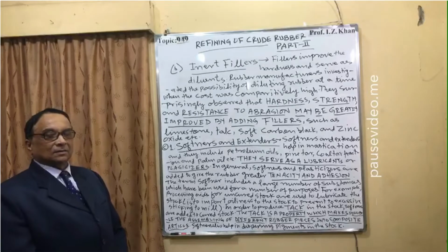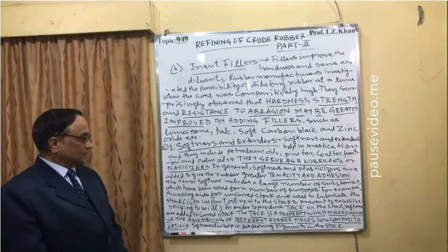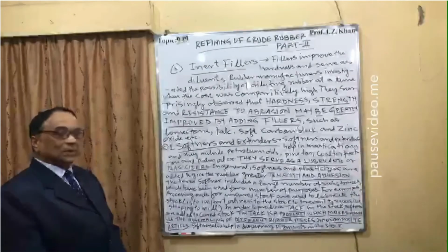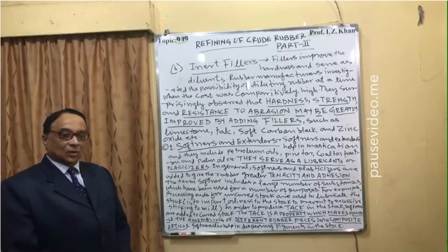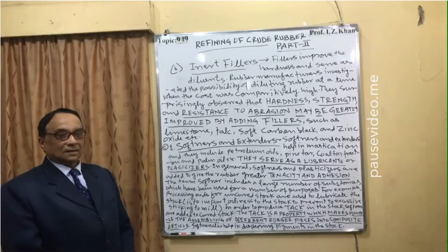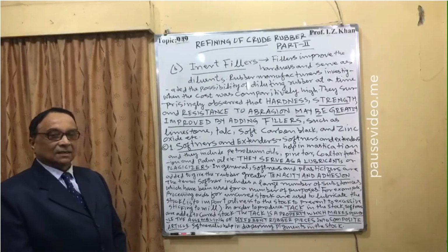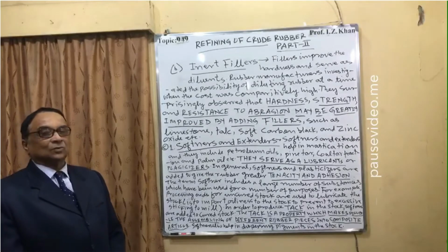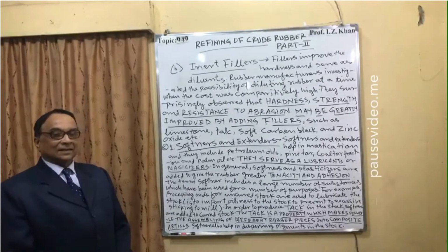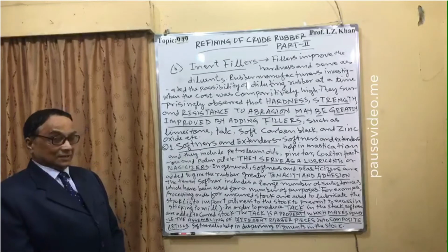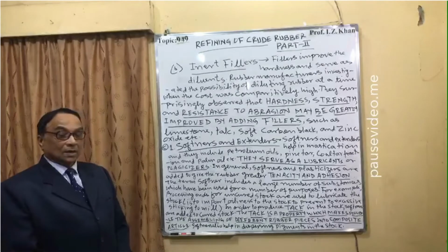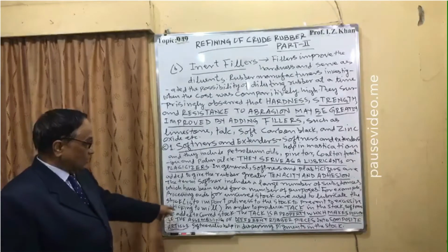Stock means the material of rubber in bulk. It is also used to prevent excessive sticking to the mill. Once rubber is under the roller and used for mastication, small pieces are added to make one sheet. In that case, sometimes the rubber sticks to the mill, calender and their blades. So once these oils are added as a softener or extender, it will not stick to the machine or the mill.